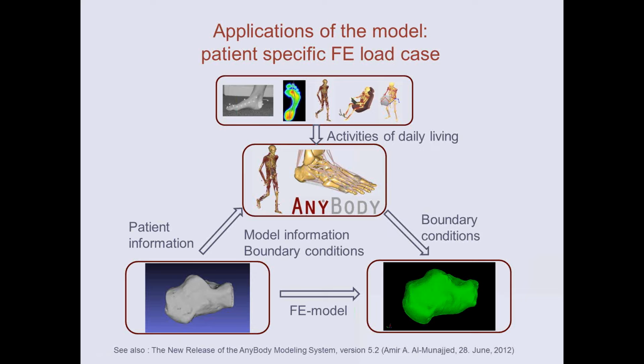the finite element software. So that's really exporting a detailed load case, because in the case of this calcaneus bone, it would include the ground reaction force, the forces of the muscles on the origin and insertion points, the forces from the ligaments, and also the joint reaction forces. So it's a very complete and in vivo-like load case that we can provide.